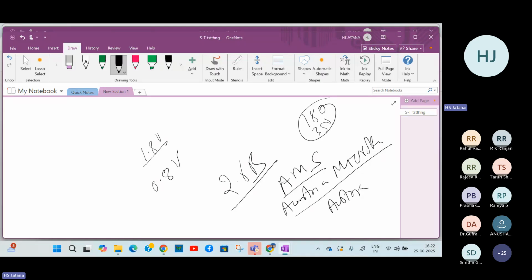Correct, sir. Lower transistors, below 45 nanometer, are pure digital and work at 800 millivolt. So noise margins are very, very small, which is not feasible. You need very highly reliable or rugged devices for space and military applications.